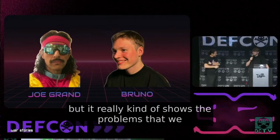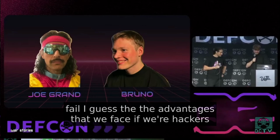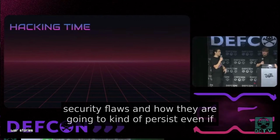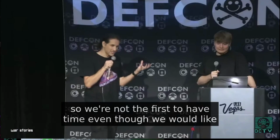I can sit back in my chair, drink some caffeine, and just play with these blocks, and test different things to see what works. The challenge with using GNU Radio is that I then need a software-defined radio to pull that data in. The sound card won't work because I need something that can listen to not only 400 kilohertz, I need to go at least double that.